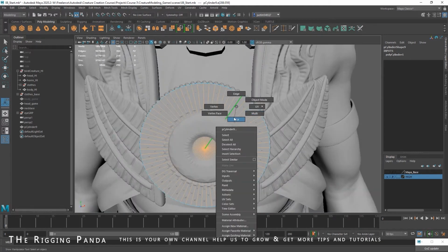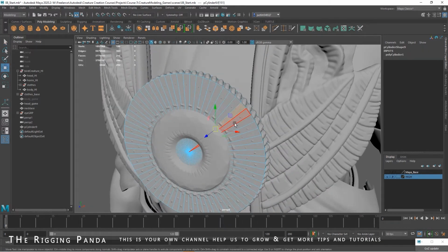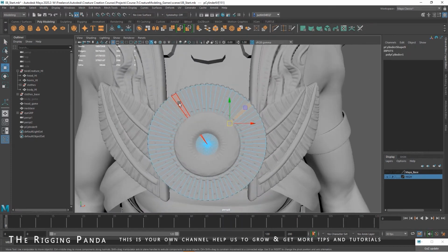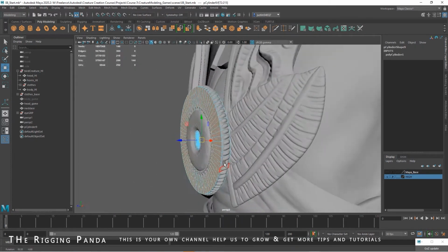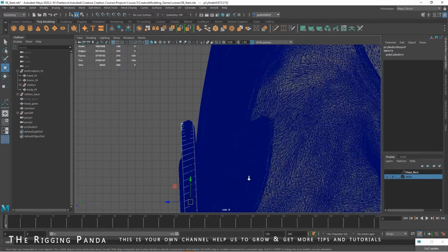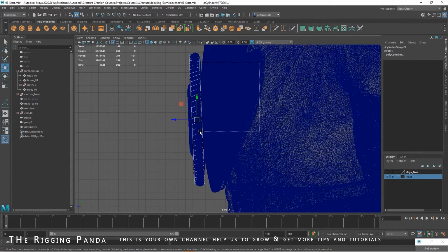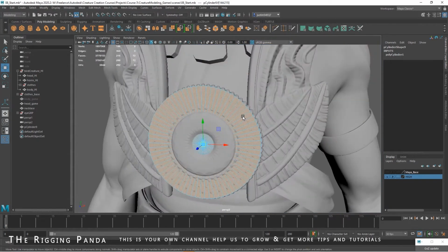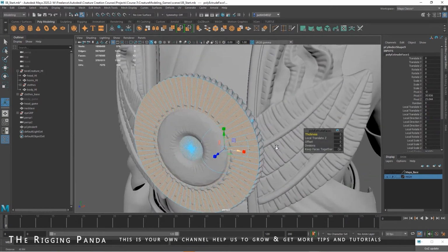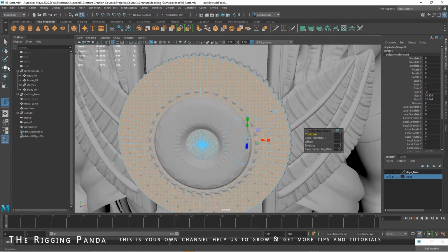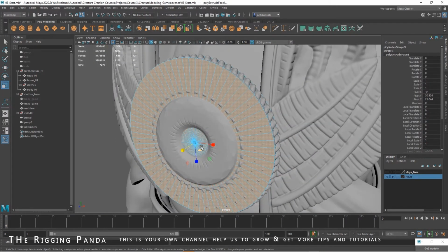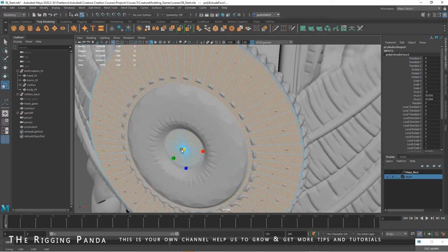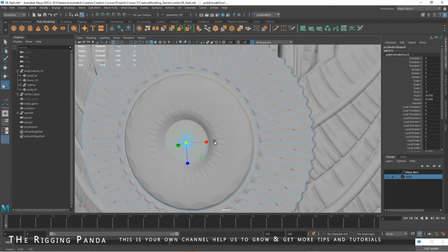And so I want to go ahead and select the faces on the front here. And so I'm going to go through and select all the faces here. And then from the side, I'm going to deselect any of the faces on the back. So I just want the front. Now I'm going to hit Control E to extrude. And let me turn off, and let me go in now and just scale this. And I'm going to scale it down so that we get a line right where that raised area starts. Okay, so something like that.